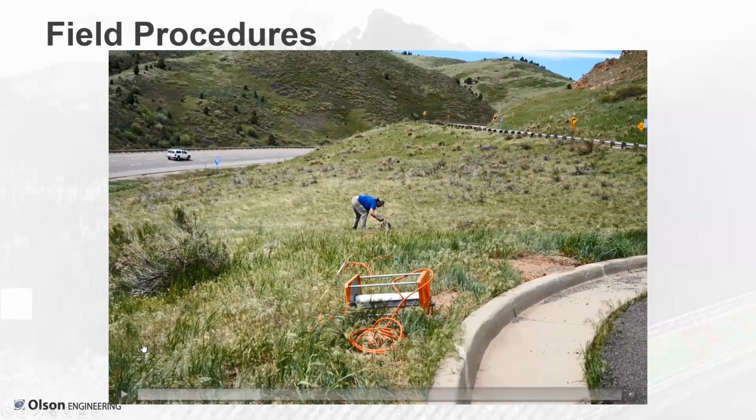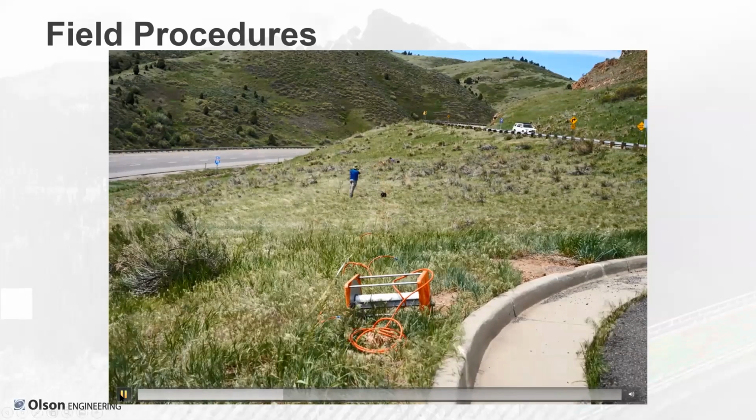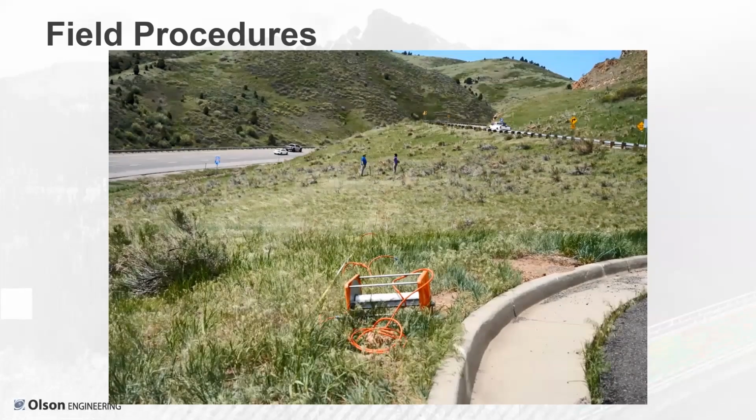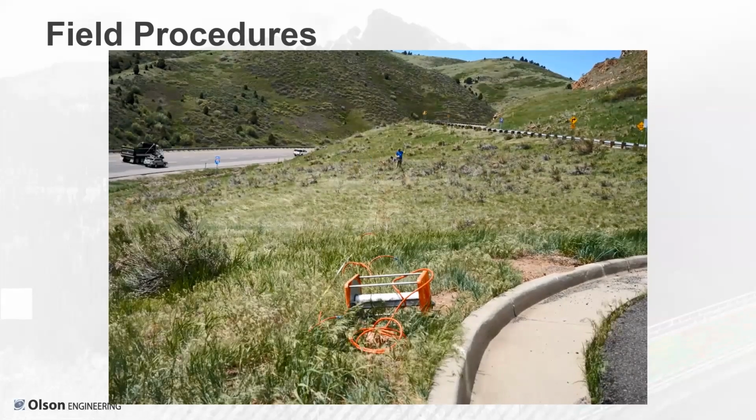What does impart a lot of noise are heavier vehicles like semi-trucks. So we time our shots so that we avoid when semi-trucks pass by. And if we do happen to get some noise from a semi-truck or another vehicle, then we can unstack the data. It's more labor intensive to do it this way, but it does improve our data quality quite a bit. So you can see Ryan's going through,